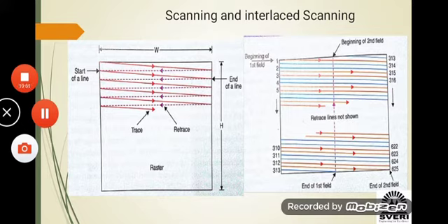In a similar way, the scanning takes place, where the beam moves from left side to right side, capturing the information. It moves very slowly, taking almost 52 microseconds to read the information. Once it has captured it, the retrace period starts, where it immediately moves back from right side to the left side, which is known as the retrace period, of 12 microseconds. So let me summarize this.